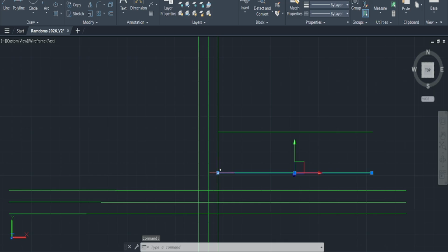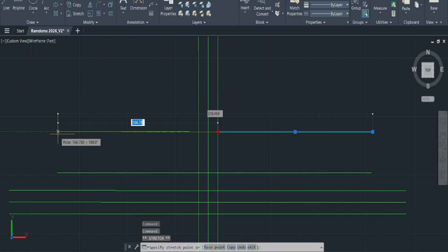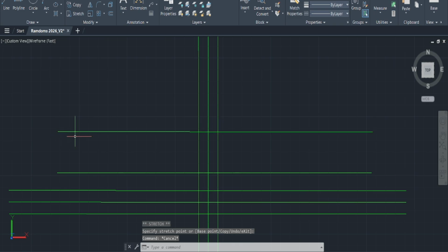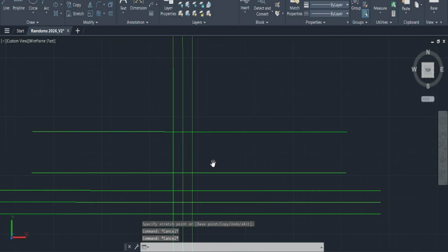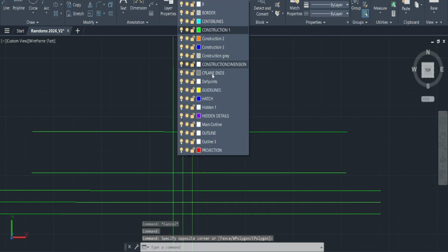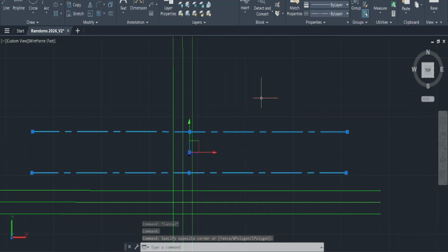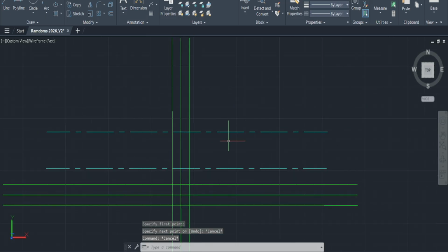I have to extend it across, but we know it's going to occur at 15 and 35 from the 15 respectively. So since I have that, I'm going to grab these, put them in center line, enter, enter. Nice, awesome. So I know these are the center of the circles respectively.